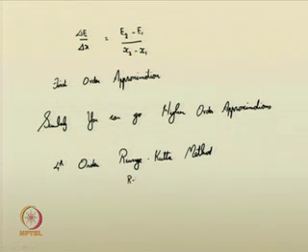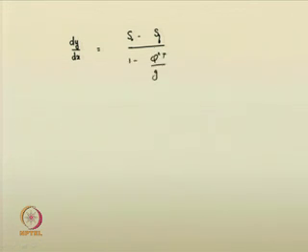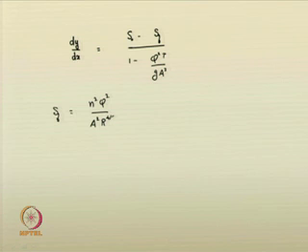It is also called the RK method. So, what is the thing? Just recall your dynamic equation, S 0 minus S f by 1 minus q squared t by g a cubed. You have seen that the energy slope or the friction slope S f is given, based on the uniform flow, as n squared q squared by a squared r to the power of 4 by 3.